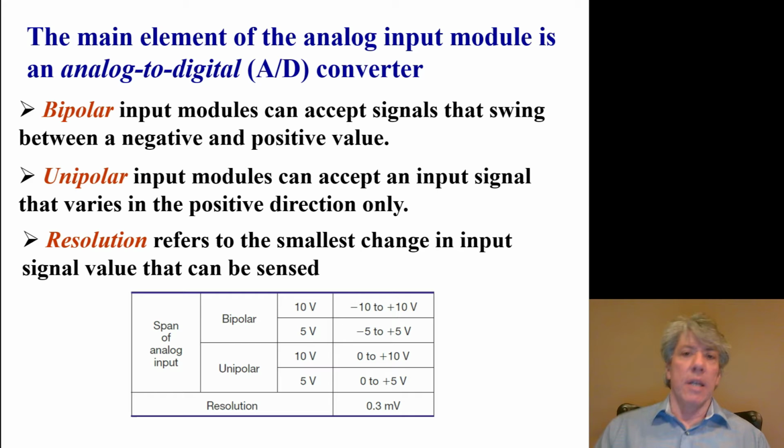That's not very common to have a bipolar current signal. What's a little more common is a bipolar voltage signal, where the voltage can go above a reference and below that same reference. Now, this is much more common in audio, and I'll show you some examples of that later, but bipolar signals are signals that can go above and below a reference level.